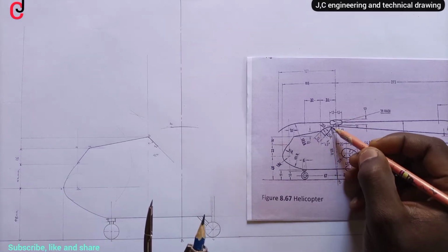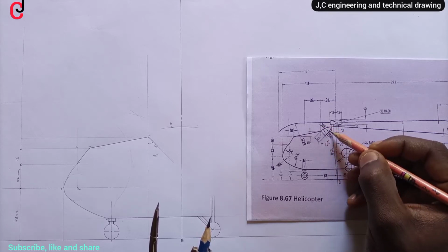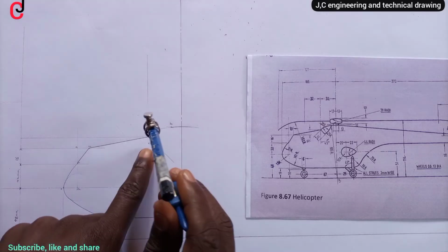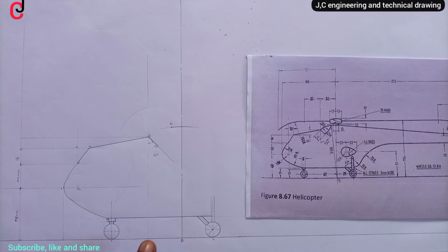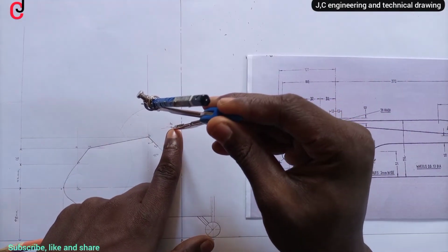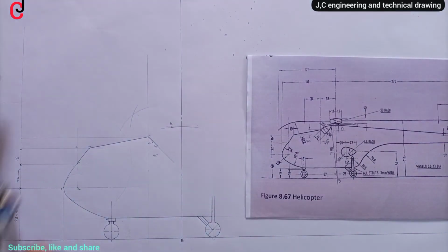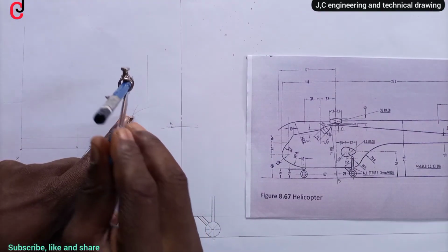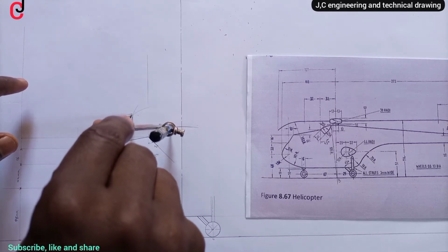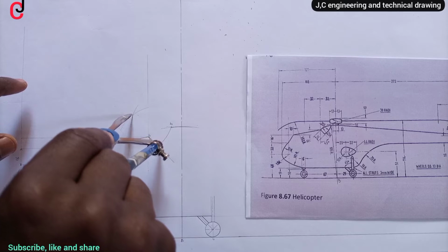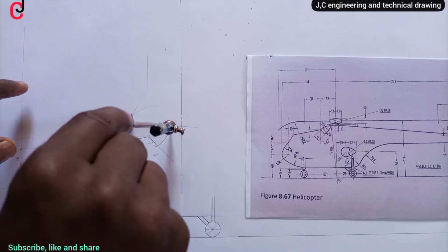B2 and B3 having a radius of 38 millimeter radius here. Place our compass pin at point B2, scribe an arc. Place our compass pin at point B3. We bisect the arc. Now using the point of the intersection, still on radius 38 millimeter, we'll join with our arc. You can see it's touching points B3 and point B2.